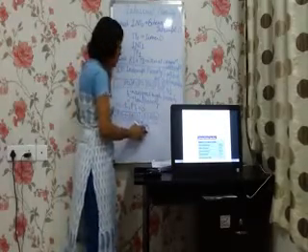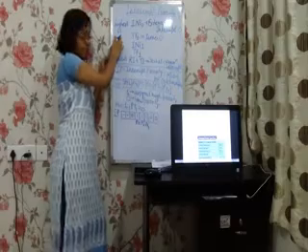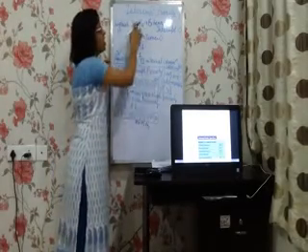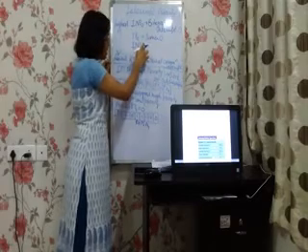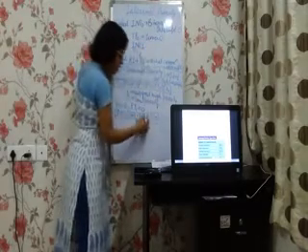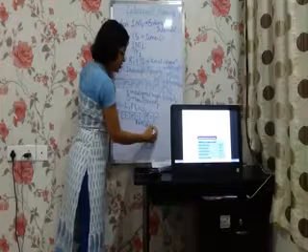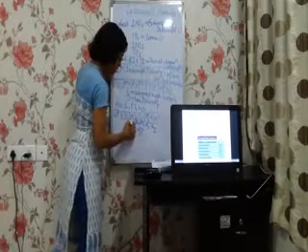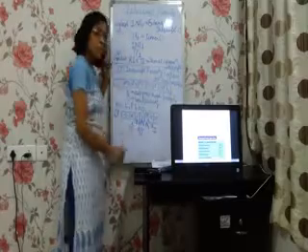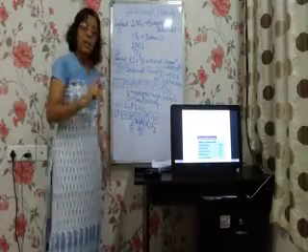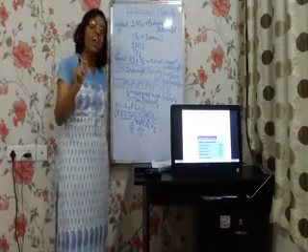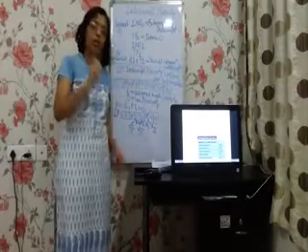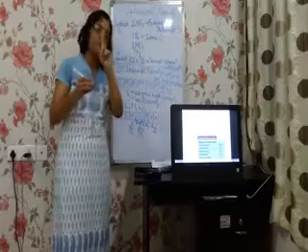It will check the default table. In the default table, out of these 3, which has the highest priority? That is the interrupt INT 1. So this will be served first, this will be served second, and this will be served last. So the IP register can be used to assign a high priority to any of the low priority interrupts by configuring that particular bit of the IP register to 1.